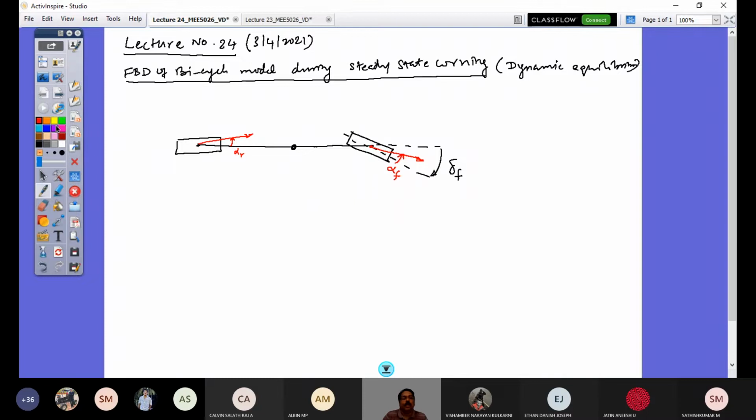Right? So if you look, this is actually the direction of wheel travel. That means this is the direction of the velocity. So the direction of velocity here is slightly not along the axis. It is also inclined like this, at an angle. And this component is u, and this component is v, and this is called the body slip angle beta.